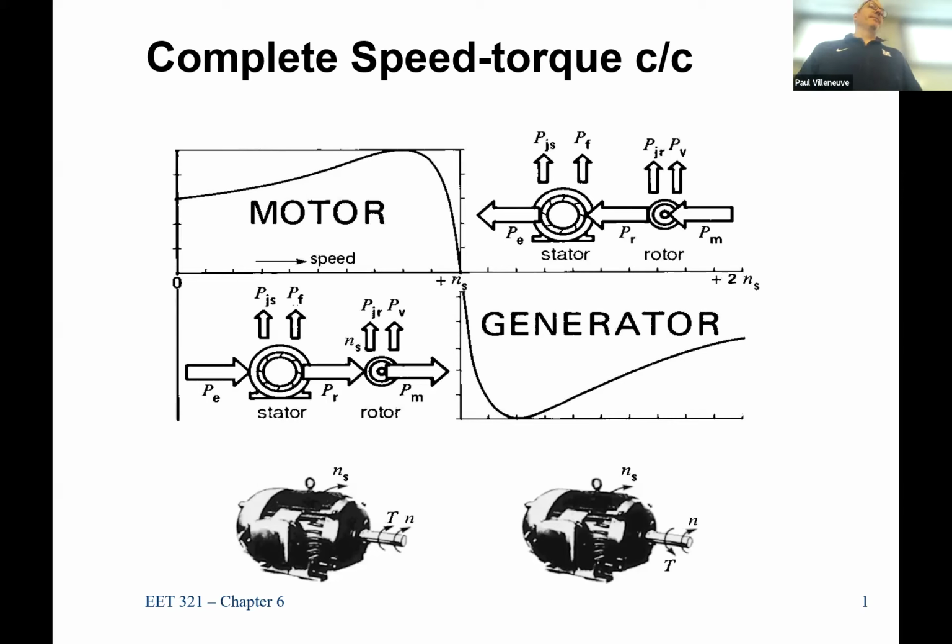But the synchronous machine, when you run it as a generator, you don't need that, because if it's synchronous, it provides its own. Yep. Okay. And that's what we were saying. So a synchronous machine can run the grid without any support. An induction machine needs some support.